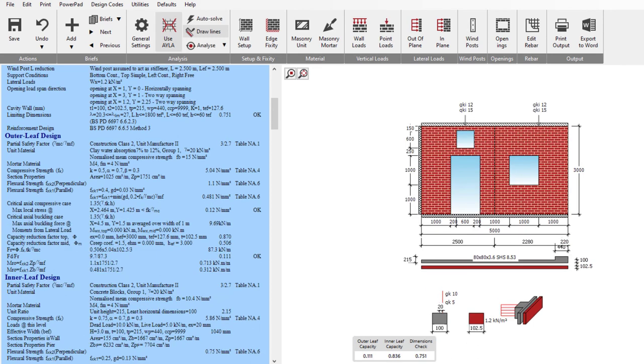What concept do you consider for your wind post? A support or a stiffener? It increases the stiffness of the whole structure. So it's still going to move, and obviously it's a yield line analysis anyway, but it is improving the moment capacity of these blocks as you go down through it.